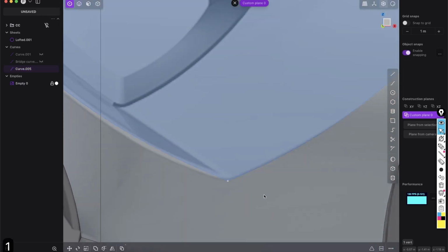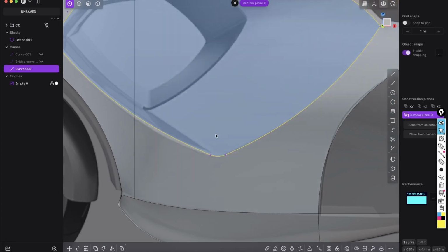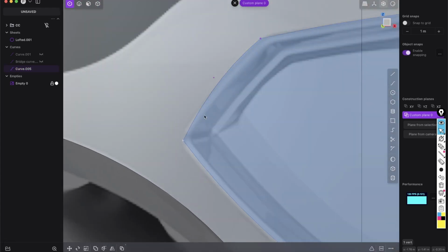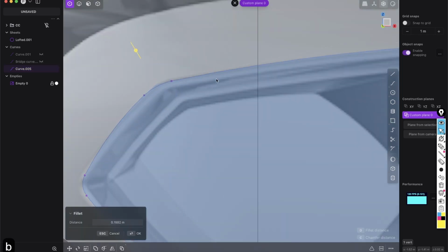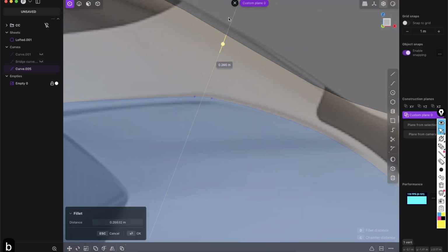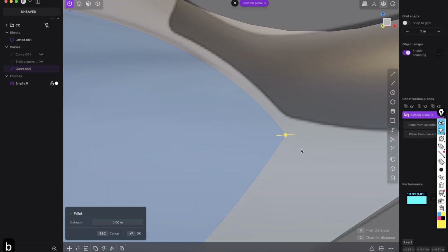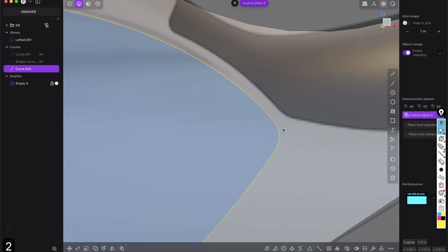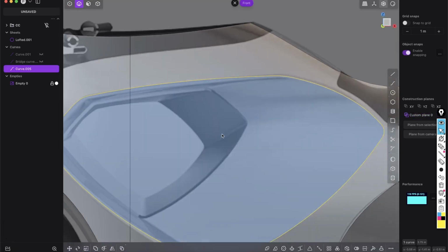So just press 1 and just go one by one. Don't select all at once because then it will just not look good. So just go where you have corners and select every point one by one to have full control over the shape. And so let's just do it quickly. Here where you have a large angle between those edges, the bevels are usually a little bit bigger. That just looks good from a design perspective. So you see we have a very nice curve here.